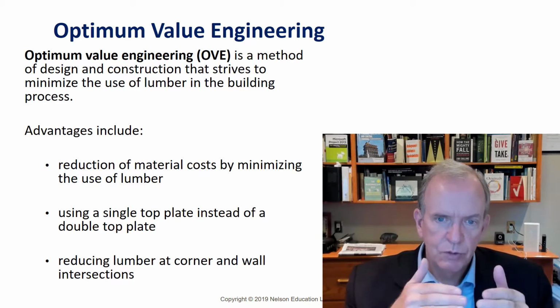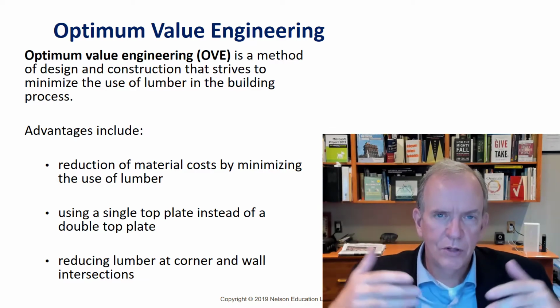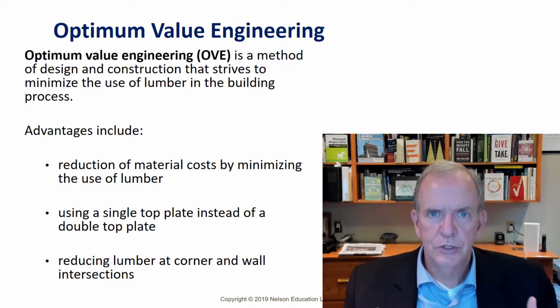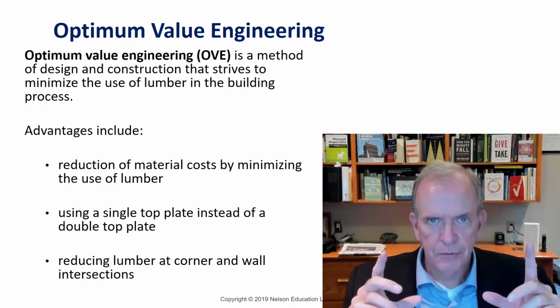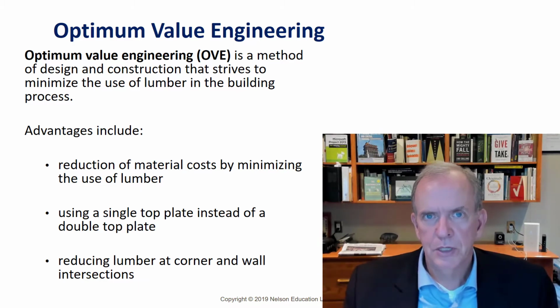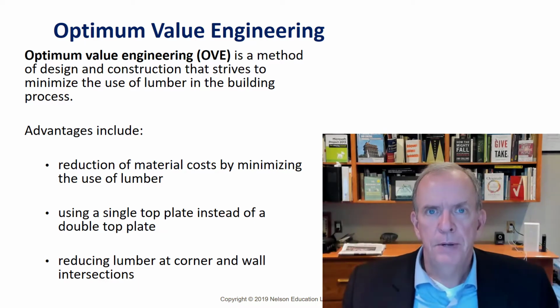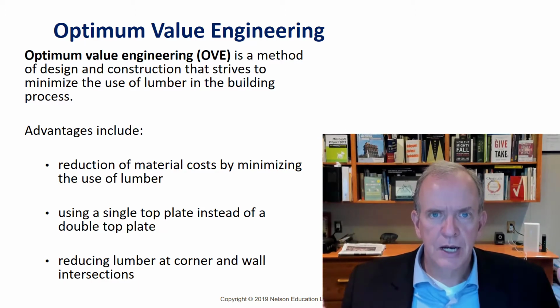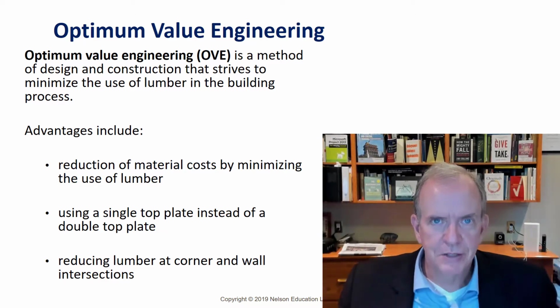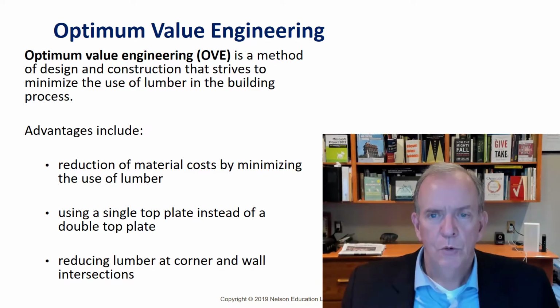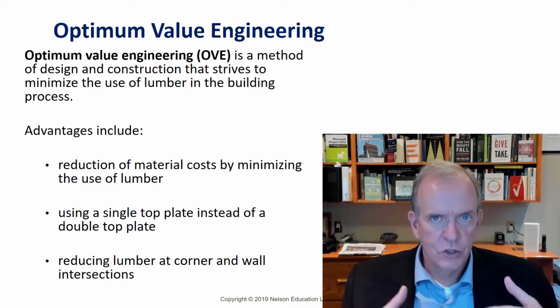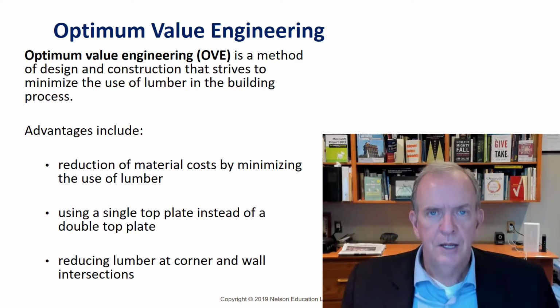And the extra stud, which goes to the outside wall, acts as a thermal bridge, so you lose heat through it. If you take a thermal imaging camera, and you can even Google that and check thermal imaging wall studs winter time, you'll see a bunch of pictures that show how when you take a picture from the outside, you can see where every stud is because it's losing heat through the wall. Whereas where the insulation is, it's not showing up bright orange or red because it's not losing that much heat.